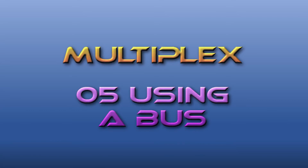Hi, my name's Dan, and this video is one of the short series of videos I'm doing about creating multiplexers, which are part of digital electronics and are a way of routing signals. Actually, let's rephrase that, a way of choosing signals. So you use a control binary input signal to choose which of several inputs gets routed to an output.